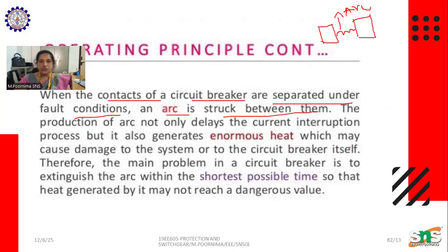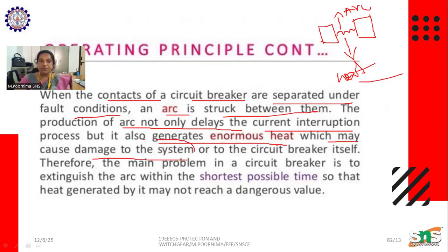The arc is produced, and the production of an arc not only delays the current interruption, but also generates enormous heat. We know the arc produces enormous heat, which may cause damage to the system or to the circuit breaker itself. This is very important.